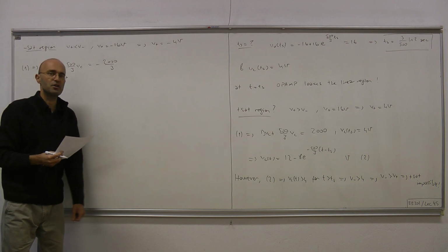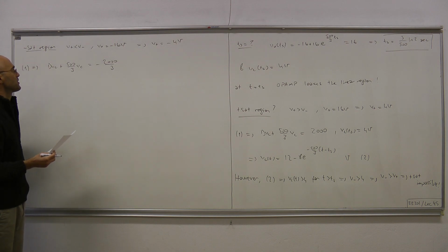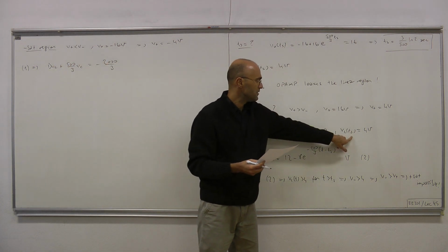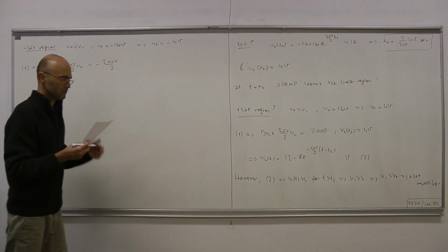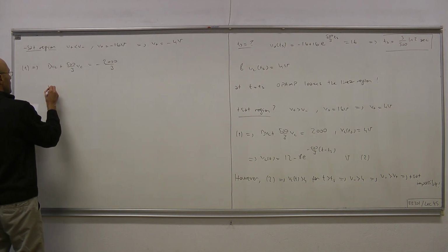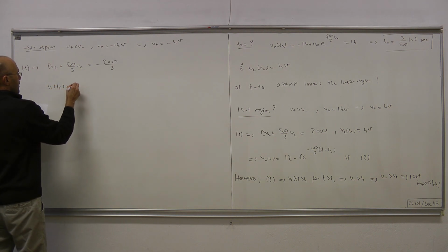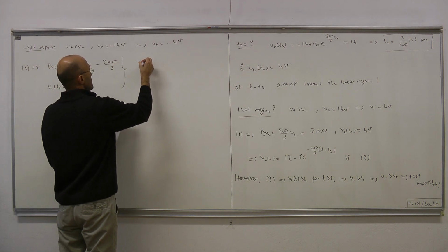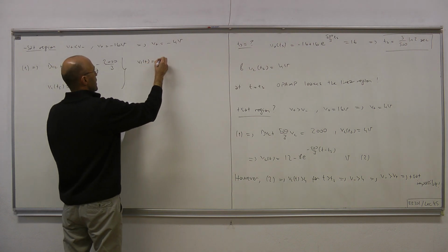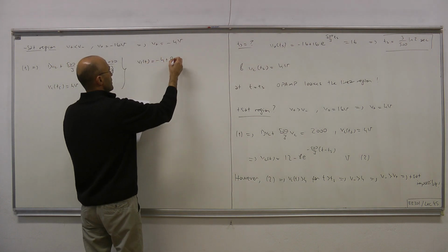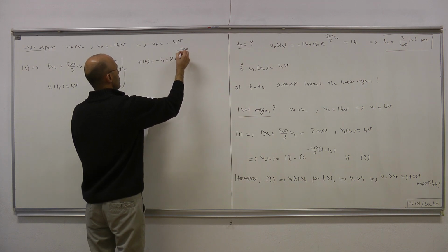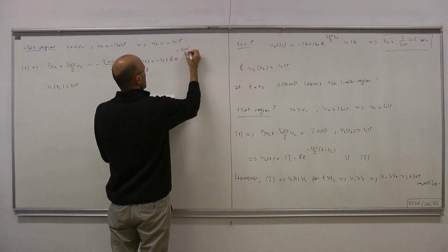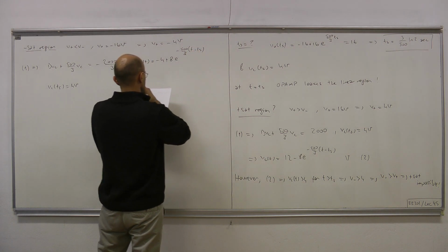Okay, first order non-homogeneous differential equation with a constant right hand side. We have the initial condition, VC(TS) equals 4 volts. Therefore, we can write down the solution easily. So VC(t) must be minus 4 plus 8 e to the minus 500 over 3, that's our natural frequency, times (t minus TS).